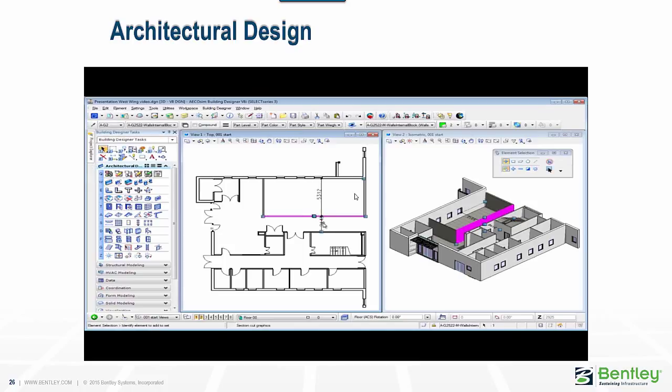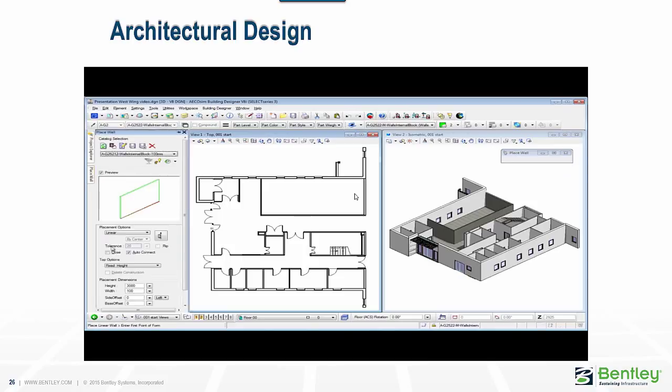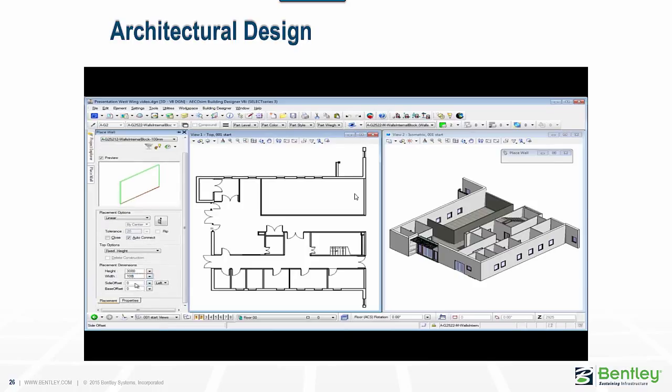Whenever you select an element, the software provides you with dimensions based on its context. These dimensions can be modified to manipulate the object. The side offset tool enables you to draw a parallel wall at a distance from the position of your cursor. This is useful while modeling circulation spaces like corridors.